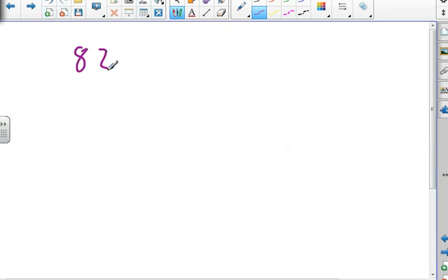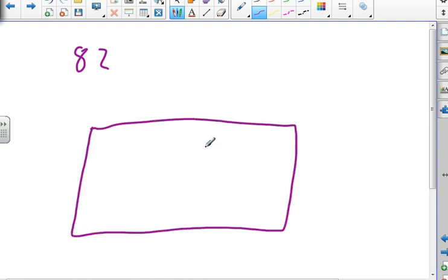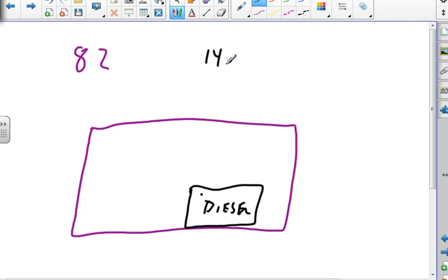This is probably page 82. One of the things you do on your submarines is you test stuff, right? So whatever it is, it has to be tested at least every year, whatever it is. So the diesel generator, so there's my diesel generator, has a low vacuum shutdown. Okay, so what is the normal pressure of the air that we're in right now? 14.8 maybe, 14.8 pounds per square inch, somewhere around there. Anyway, so it has a low pressure shutdown at 11 pounds per square inch.